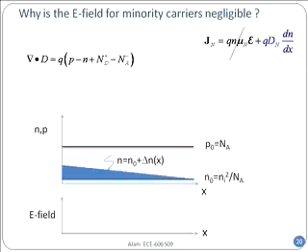So you remember that in the middle section, light was shining. It generated electron-hole pairs, G multiplied by tau sub n. That was the extra carriers. And it was sort of coming out in region 1 and region 2 contact sites. Let me assume that it was coming out with some sort of linear profile in the trap-free region.